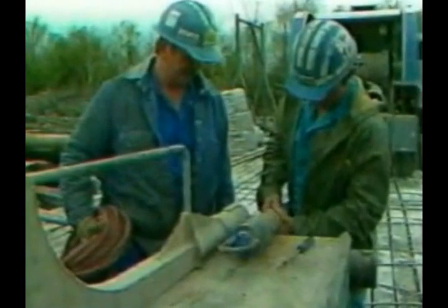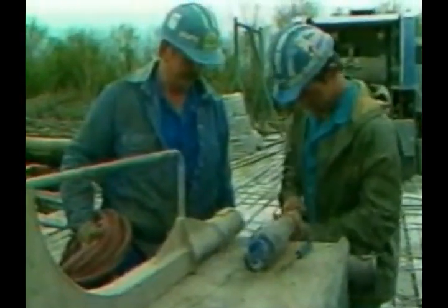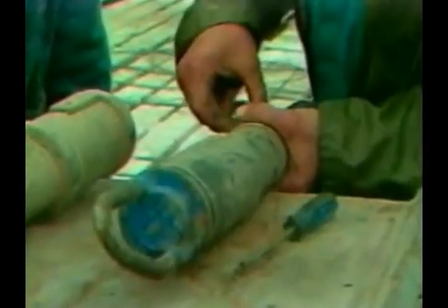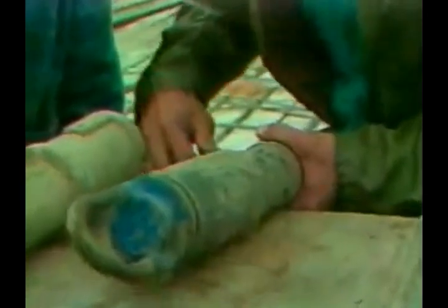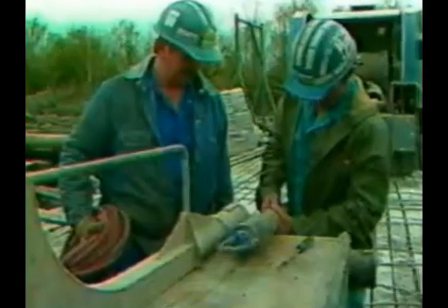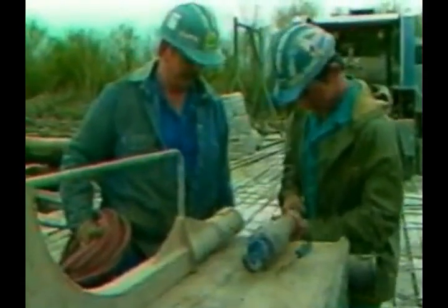A multi-conductor logging cable serves to physically and electrically connect the logging tools with a logging unit. The cable attachment mechanism, shown here, or head as it is called, is also designed to be the downhole weak link or break point of the cable system. Should the tool string become stuck in the hole, this weak link is designed to break before the cable snaps, avoiding costly fishing jobs for wireline.